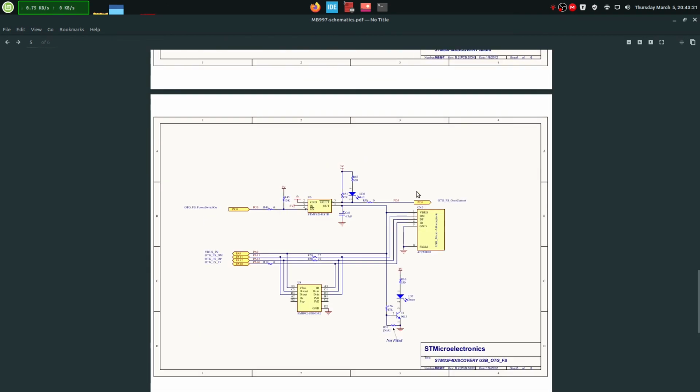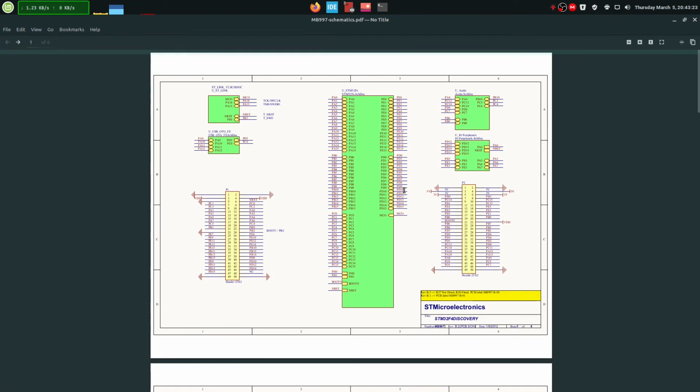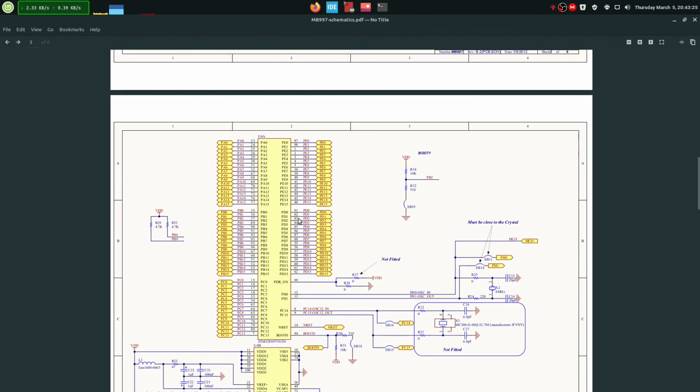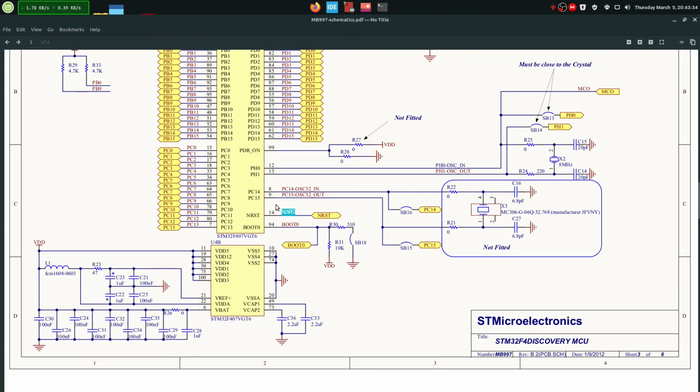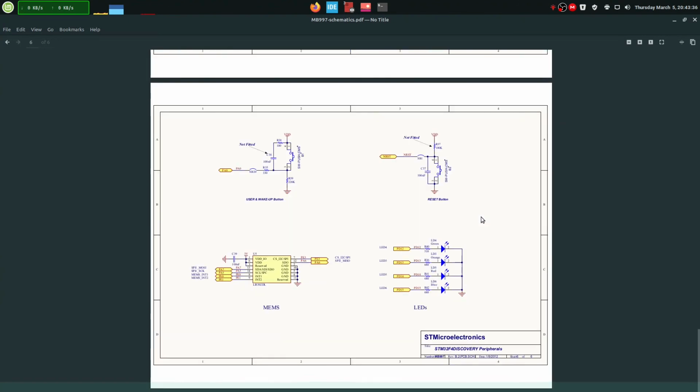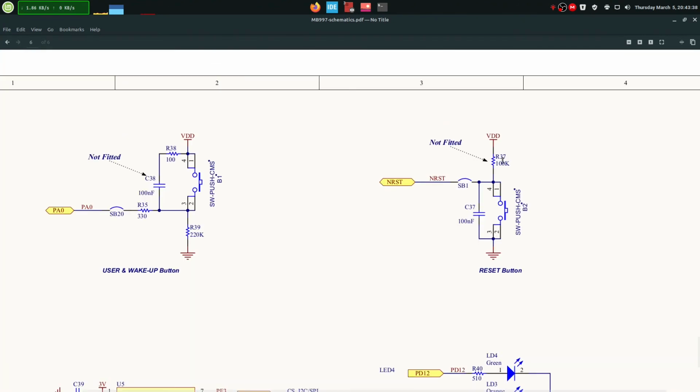So just not to make any confusion, let's go to the processor up here. Where is it? Here. And let's find the damn reset, which is over here. Okay, so this reset should be put to high. There's no resistor here, so that label is probably not correct. This 100K should be fitted in order for this processor to work. If you want to reset it, you have to pull it low. So there's this button. When this button clicks, this pin goes low.